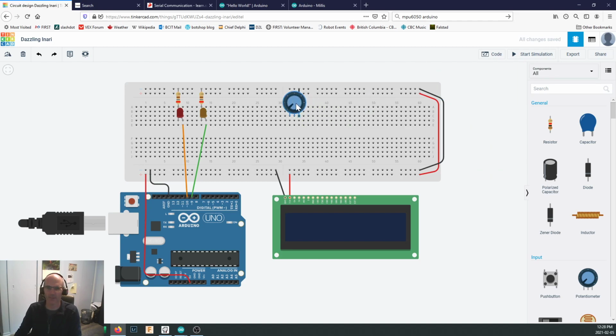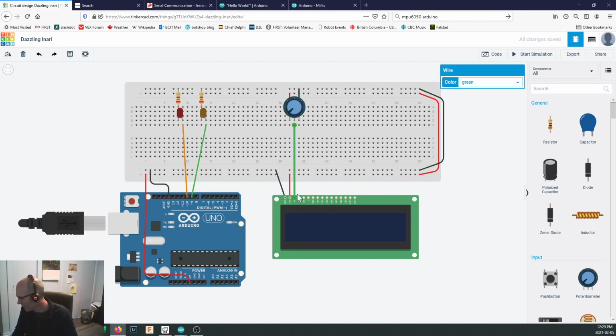I'm going to drag my potentiometer over here and put it right between those two. So here we have our red line comes in here. This side of the potentiometer will be at +5. This side will be at ground. And as we turn the dial on our potentiometer when it's running, we can take this middle, the wiper, and kind of sweep it from the 5 side down to the ground side. And that's going to give us a voltage output that we can tie right now into our contrast pin, right down here. Okay, and for that, I'm just going to leave the wire green.